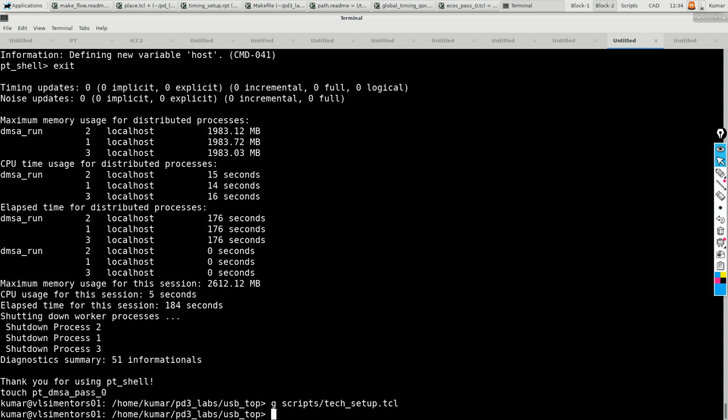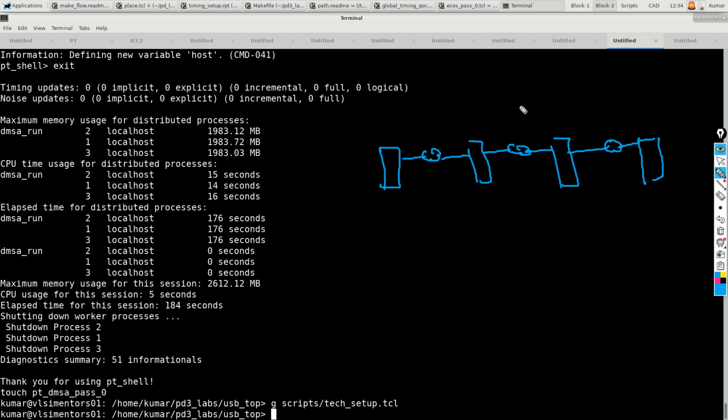So now to test it, you need to have different methods. One is scan shifting, so there is stuck-at fault, and then there is transition fault, and then there are different ways of identifying the faults. And you may have lakhs and lakhs of paths. Say simple, you may have a design like this, and there may be paths like this in terms of lakhs and lakhs. Now say there may be a failure over here. How do you identify that this is the path that is actually failing?